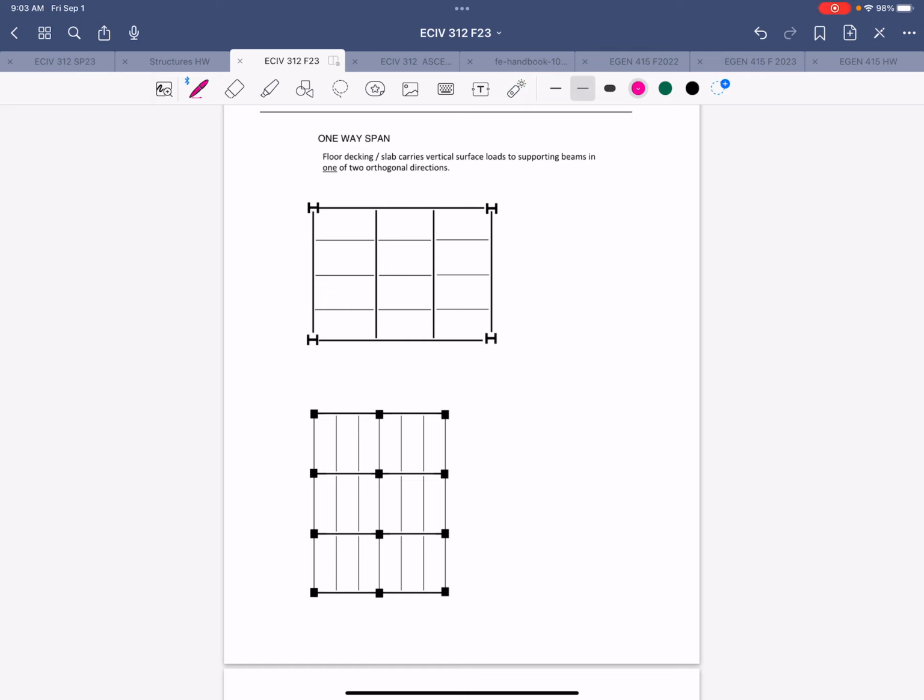And the way we can tell this just by looking at the floor plan, there are a couple of clues. One, you can see that there are some gaps at the ends of these beams where they hit the girder lines. So that's an indicator that those beams are supported by the ones that don't have the gaps there.